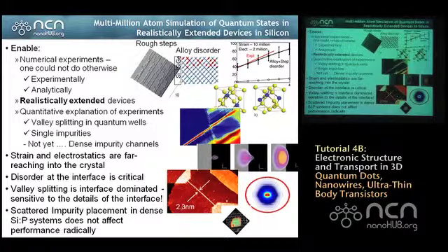Like here, this is a photograph in the production process. At the end, the phosphorus is buried like 10, 20, 30 nanometers under the surface. So this is a buried metallic wire. It doesn't have surfaces. How about the interfaces? Well, there's almost no strain. The phosphorus fits almost perfectly in silicon, so it doesn't even cause strain. There are no broken bonds. It's a perfect crystal.